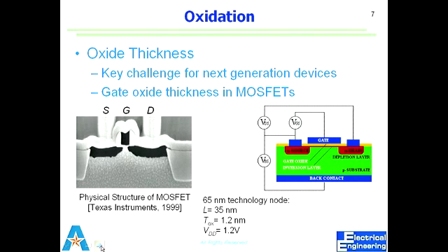So again, this device, we probably don't have to go through the physics of it, but the basic structure is something we have to be familiar with. Right? So there is a source region, a drain region, a gate, and these regions are heavily doped with a type which is different than the substrate. So P-type substrate, we have N-type device in there. That's the idea of complementary MOS, CMOS. Anyway, oxidation or oxide thickness is one of the critical factors in the whole device technology.